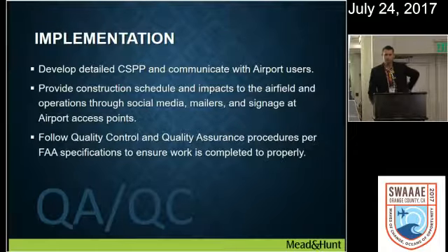And so talking with a few different folks around the country, I think the best solution that has come across is actually sandblasting. And then obviously it creates another cleanup measure, but the sandblasting is the only one that really gets into those grooves, into those pores within the asphalt. And then after you do the cleanup, of course, you go back and apply a fog seal treatment.